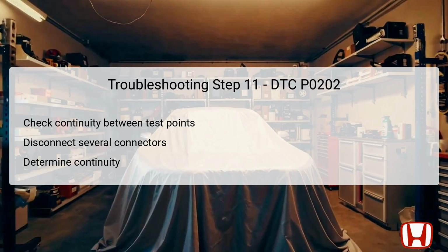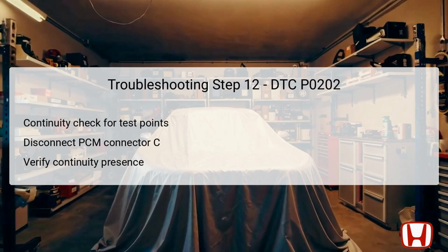For Step 12, you will need to leave the vehicle in the off-lock mode and disconnect the PCM connector C51P. The next check involves continuity between injector control module connector C12P number 4 and PCM connector C51P number 19. This test wraps around verifying the INJ-F3 line for continuity.